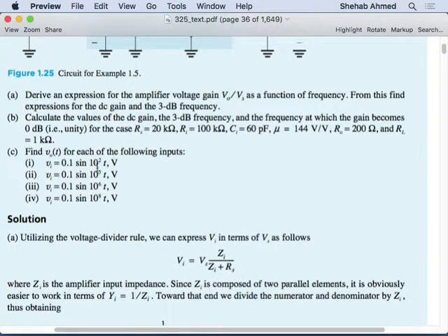So for these two, the gain of the signal will be the DC gain. So it will be 100 in decimals, or 40 dB in decibels. And then these two, one is at the corner frequency and one is higher than the corner frequency. Corner frequency is 10 to the 6. 10 to the 6 times 10 is 10 to the 7. 10 to the 7th times 10 is 10 to the 8th. So I expect that here I lost my 40 dB completely, right? I went 2 decades above. So this will be the unity gain response. It will have a unity gain response to this signal, right?